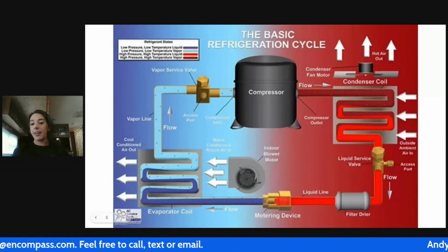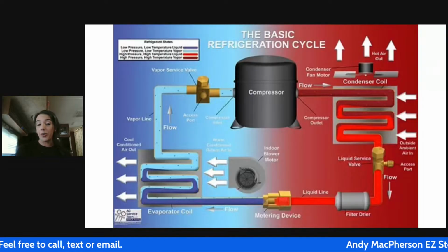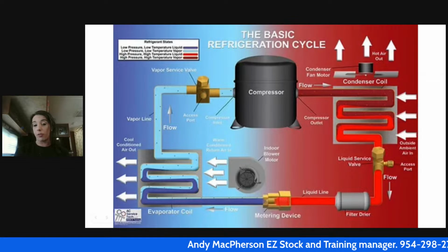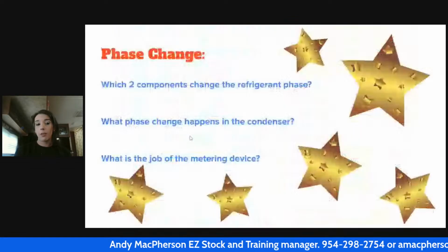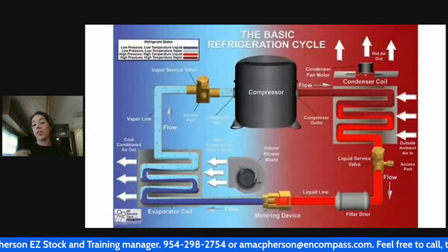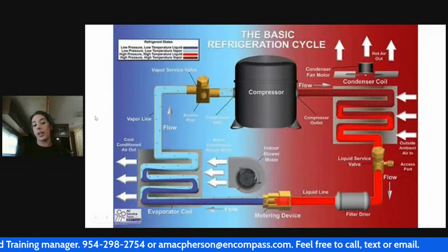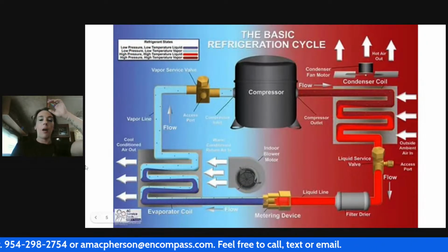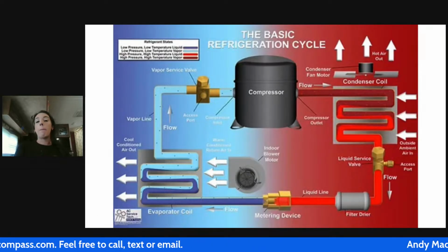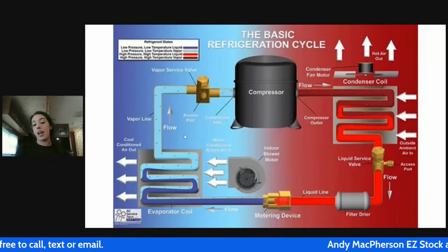Now, on the flip side, if I find that evaporator at 57 degrees, I can surmise that I either have an overcharge, too much refrigerant in the entire system, or I have some sort of weird suction line restriction that is filling my evaporator. We won't get into all the nitty gritty of crazy things that can happen because I have seen it all. But for the most part, you're going to see a frozen evaporator.